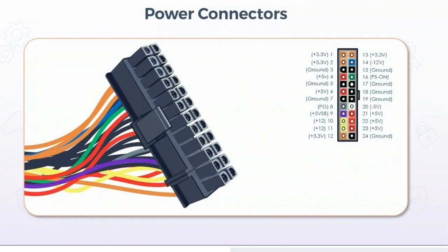Now, the power connector depicted here does not refer to the power button on the front or the top of your computer case. Rather, this is the main power connector for the motherboard itself, which comes directly from the main power supply. This particular example is a 20-pin Molex connector, and it would fit into a specially keyed socket on the motherboard so that it couldn't be installed in the wrong orientation. And there was a small tab release on the side which clicked into place when fully inserted.